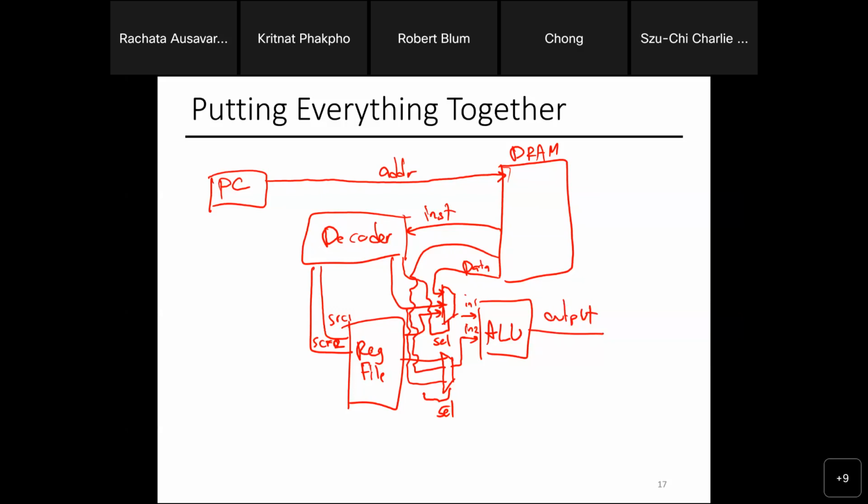So one of the potential locations for my output is going back to the register file, right? Can I go to the memory? Let's say I have some output, I want to write it back to the memory. I can. If I want to, I can also have an output that goes into the memory here as well, right? Then the decoder would decide, do I actually enable that wire or do I disable it? Make sure it doesn't go to the memory.